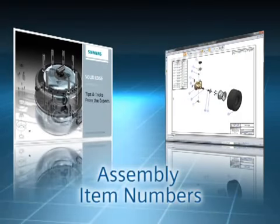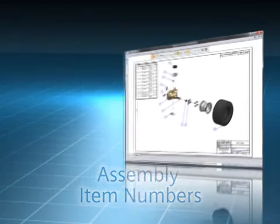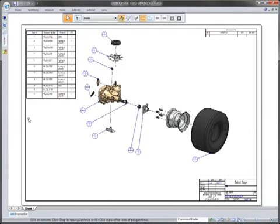It's standard practice these days to derive a bill of materials on a 2D drawing from a 3D assembly model. But did you know, since Solid Edge ST3, it's possible to drive the item numbers from the 3D assembly while you design. In this tip, I'm joined by Kyle Arruda to show you how.